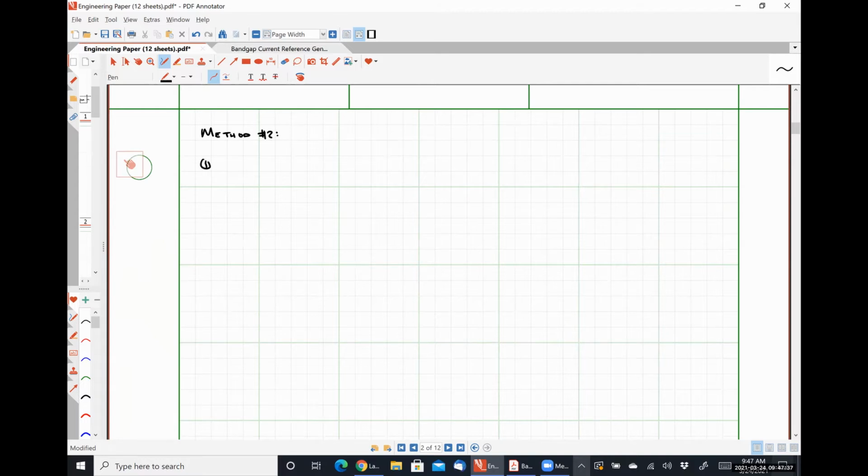First step would be to calculate R out. So for our circuit, that would mean we short out our input, which was applied at the emitter. So our emitter is grounded.